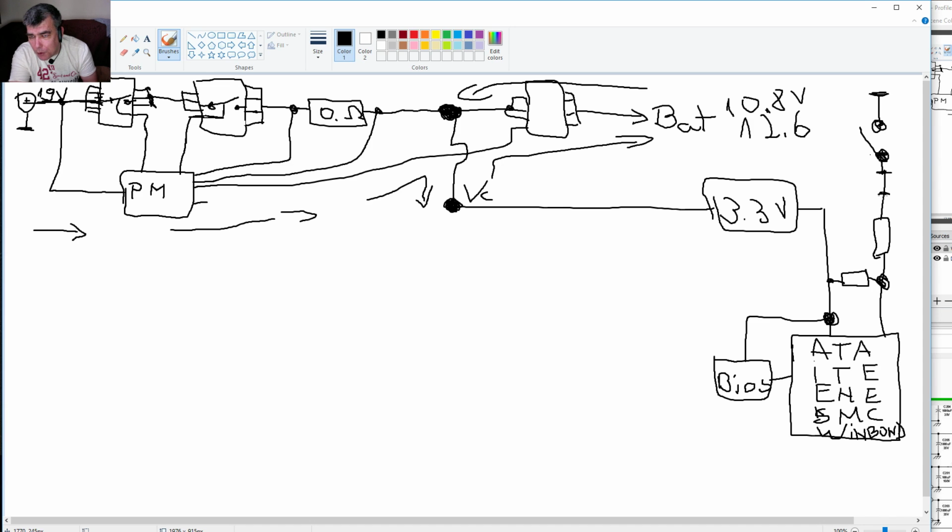You can make a short from this pin. If you check with the multimeter, you'll have 3.3 volts because you have this voltage, yeah? And the pin is not going straight into the chip, so you cannot damage anything. You can short that pin to ground to start up the laptop, yeah? That's the power button, that's the way this chip is working. Also, this chip is doing more things after you press the power button, yeah?